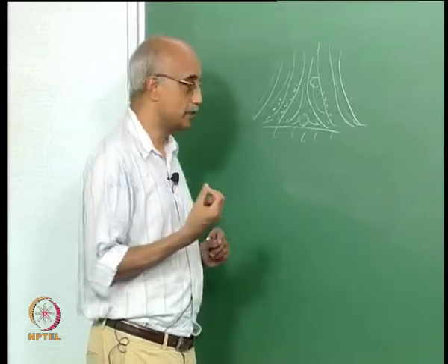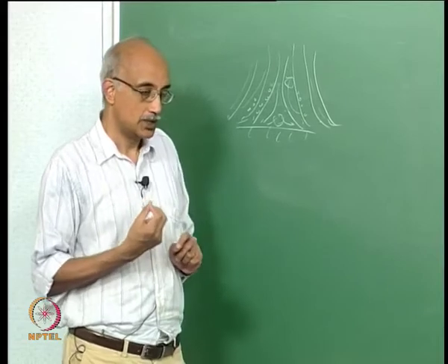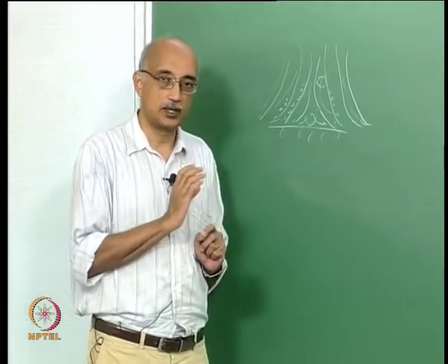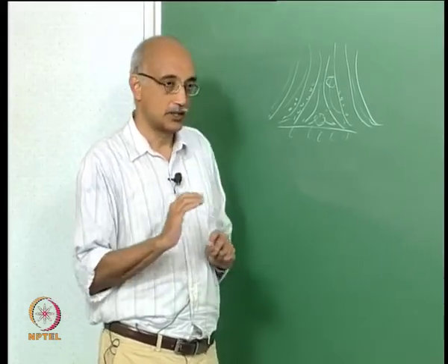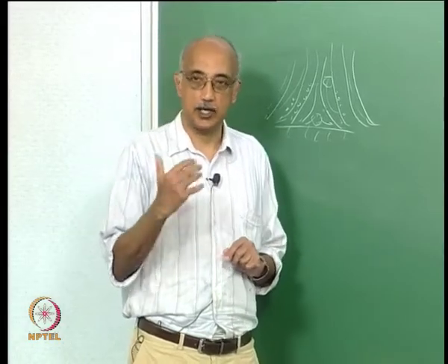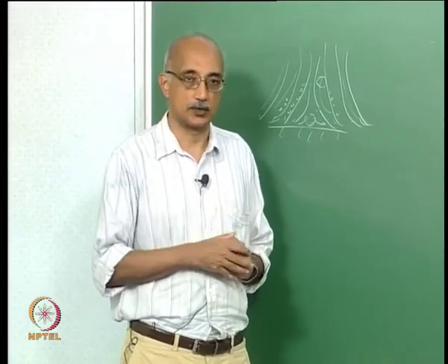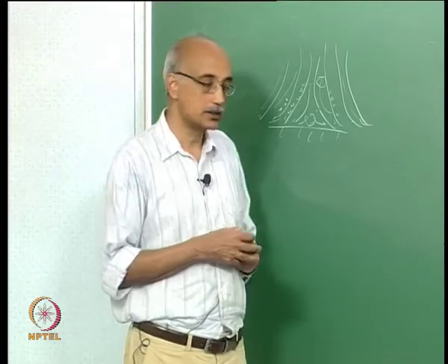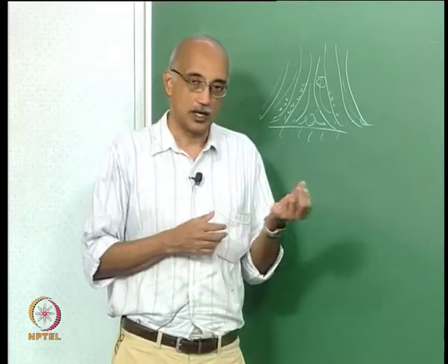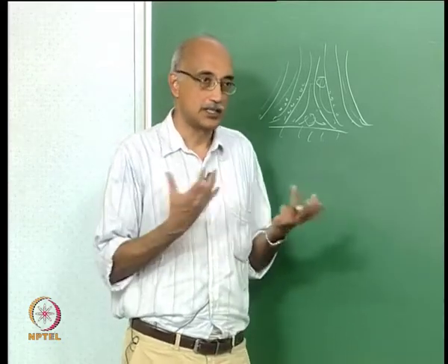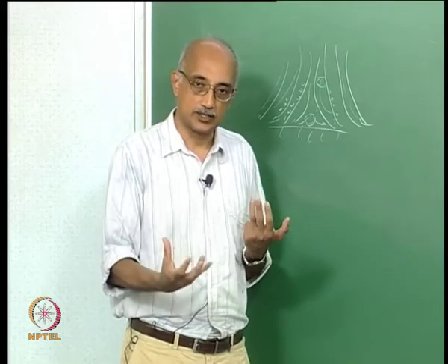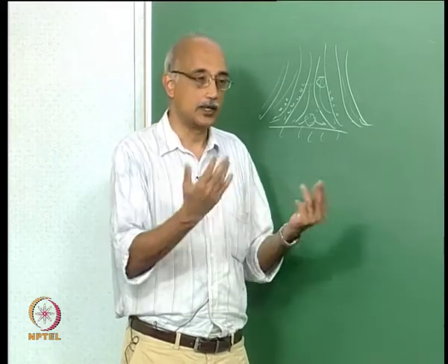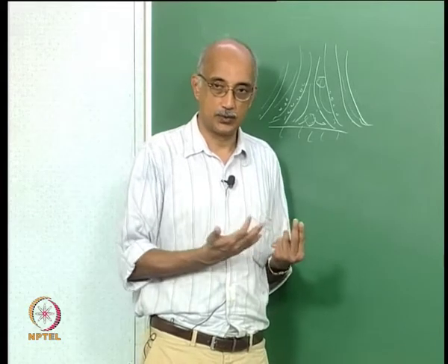So the measure of inertia is really the tendency of the particle to behave in a fashion that is completely different from the carrier fluid in terms of its transport characteristics. And inertial effects will obviously depend on the size of the particle. As the particle gets larger, it will have a greater tendency to separate itself from fluid streamlines.